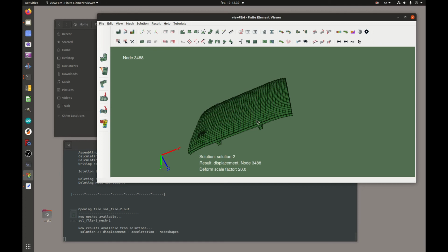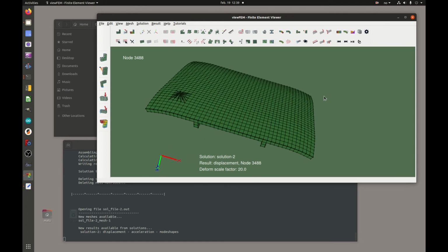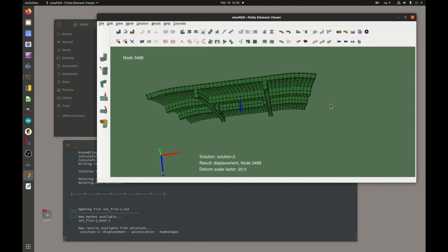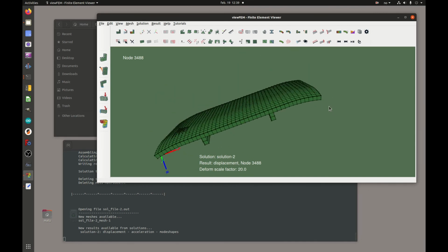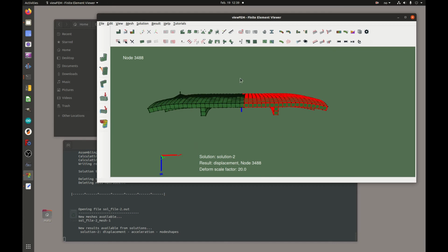So that does it for this tutorial number 7. You now know how to create a new hex mesh, and of course, should you want to use different elements, sometimes you just need to use tet elements, because there's no hourglass control here.